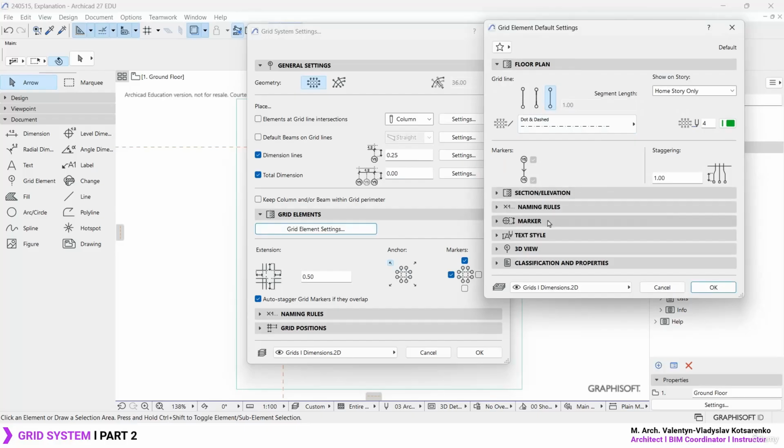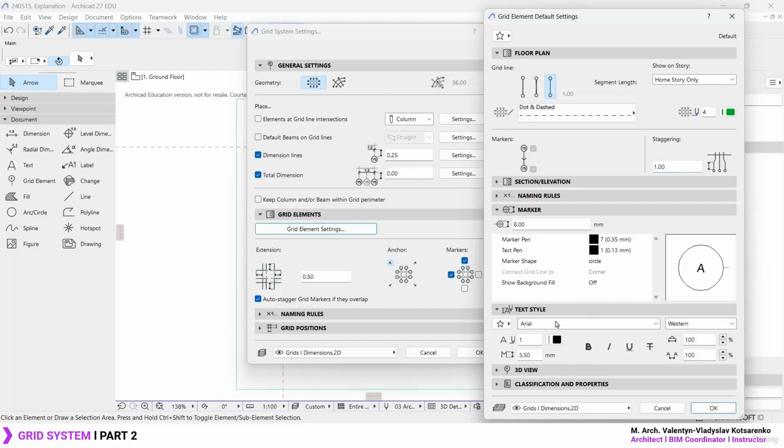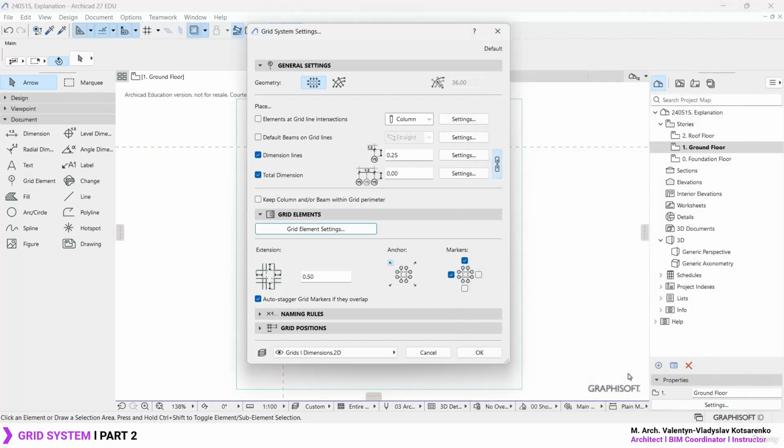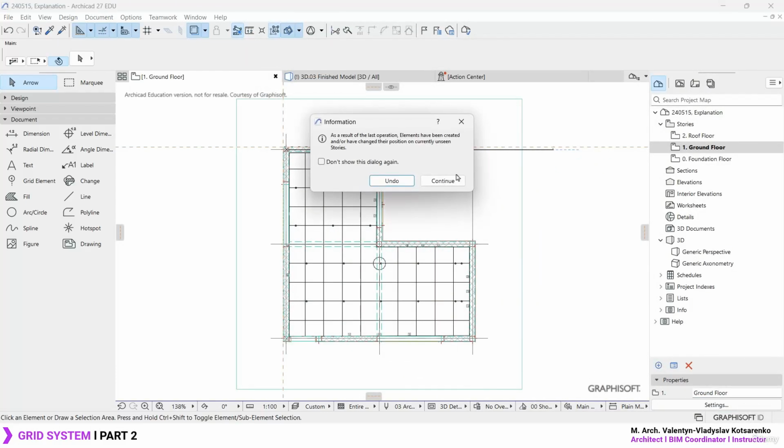the grids over here. And for the markers, how about we make it a little bit less, maybe 8 millimeters, and the text is going to sit at 6, 10 millimeters over here, or 12 millimeters. I think this is the base formula I usually use, so I'm just going to set it 6 and 12. If it's still too big, we also need to adjust the scale, make it 175, 150. So let's simply press OK, and hopefully we can achieve it on this round.